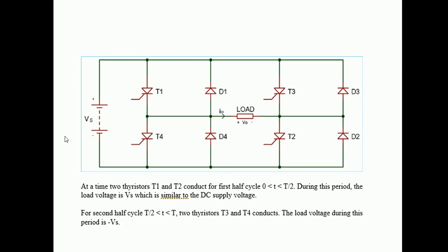Please also note that if T1 and T4 accidentally get turned on simultaneously, then the supply will get shorted. So we have to prevent this: T1 and T4 must not be on at the same time. Similarly, T3 and T2.